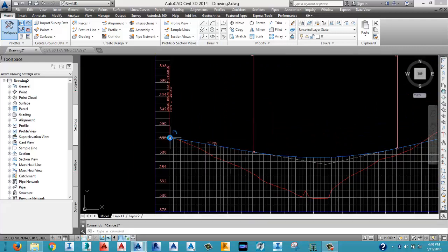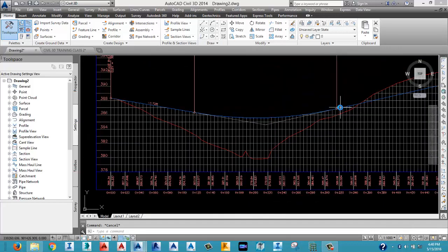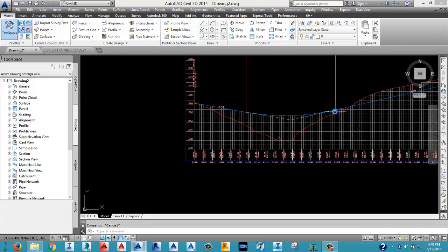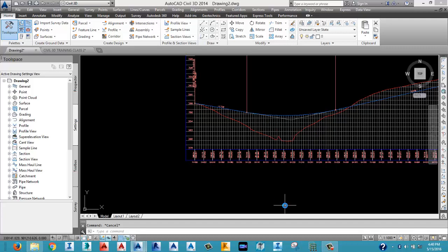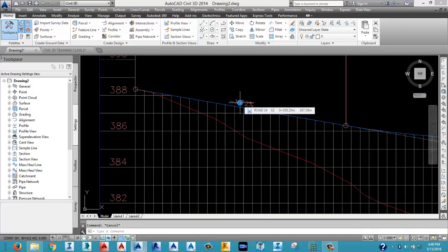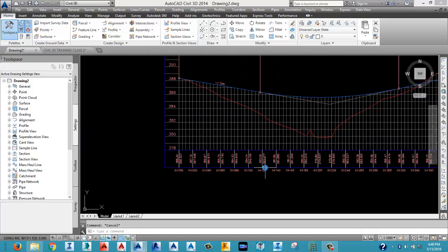See my start point. My next point I'm dropping is almost at 200 meters. Here you get, the next point I dropped was almost at 200 meters. I didn't drop at 50 meters because you can't expect a sudden change in grade whenever you're traversing a road. 50 meters is just like here to the front of that gate. So you don't expect a sudden change of road, because if I'm saying a change of maybe 1% now, within this particular 1% coming down up to this point, which is 120 meters, is okay.